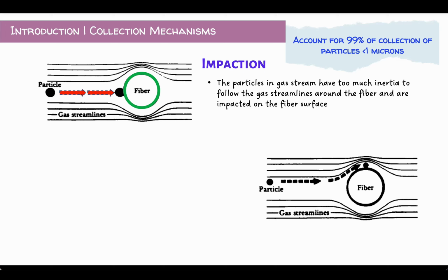It is effective in fabric filters because there are many sharp changes in flow direction as the gas stream moves around the various particles and fibers. Unlike some types of particulate collection devices, there are multiple opportunities for particle impaction due to the numbers of individual dust-caked particles and fabric fibers in the gas stream path.